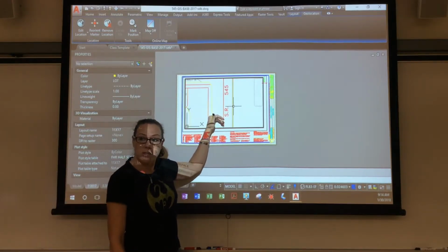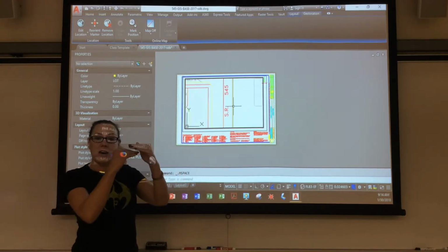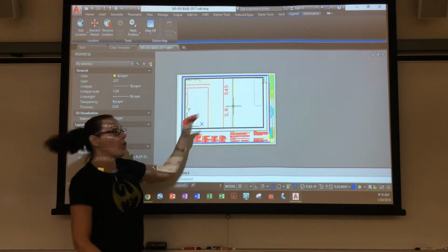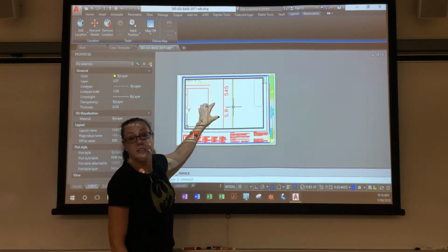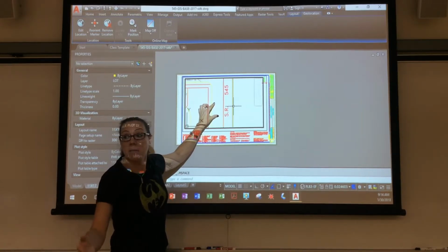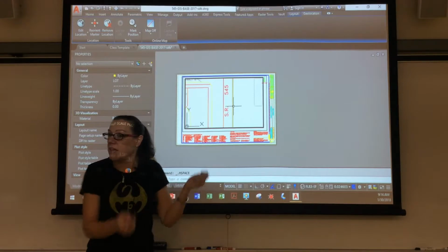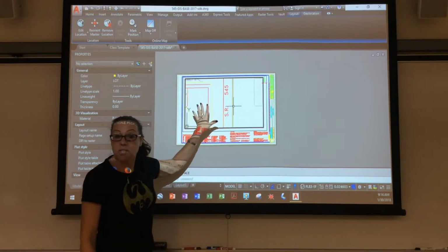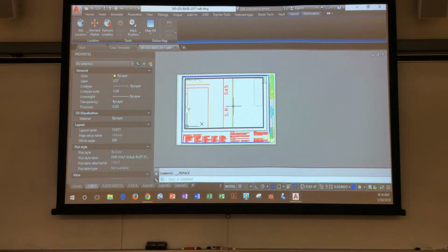We wrote the numbers, because written information is in a hierarchy of what's on the drawing. Written information overrules scaled information. So we said 105 feet of such and such pipe. When they scaled it, they only got 90 feet. Then it was not our fault. We still told them, yes, our scale was wrong. But that led to a whole discussion on what we need to do.